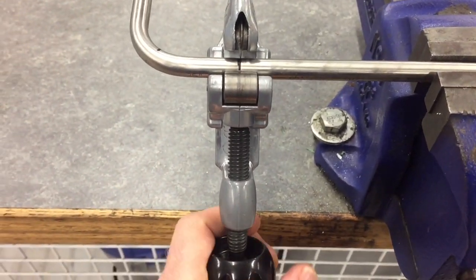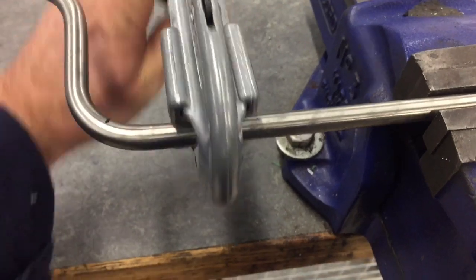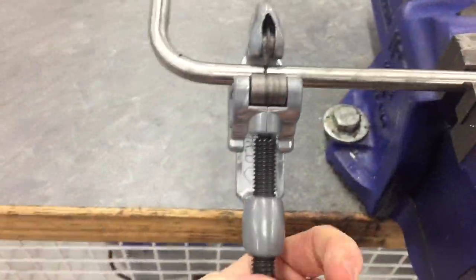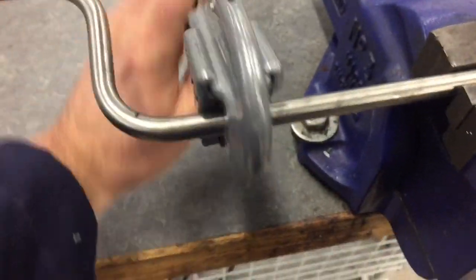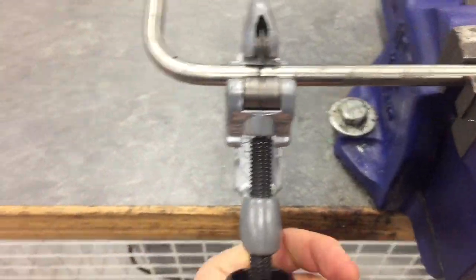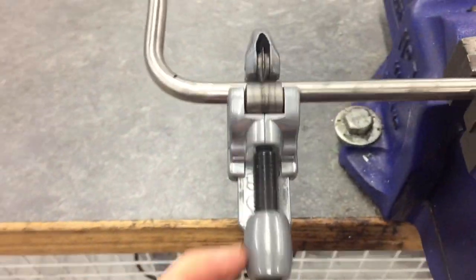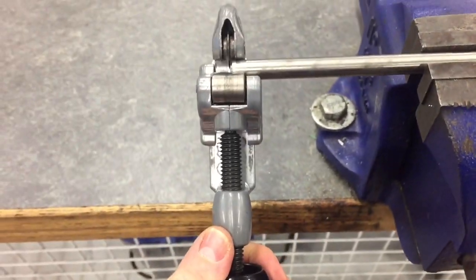You'll feel it loosen off. Turn the handle probably about 1/4 or 1/2 turn, and keep doing that. Tighten it again. Keep doing that. Keep turning it, about two rotations approximately, and then tighten it again until eventually the tubing cuts and falls off.